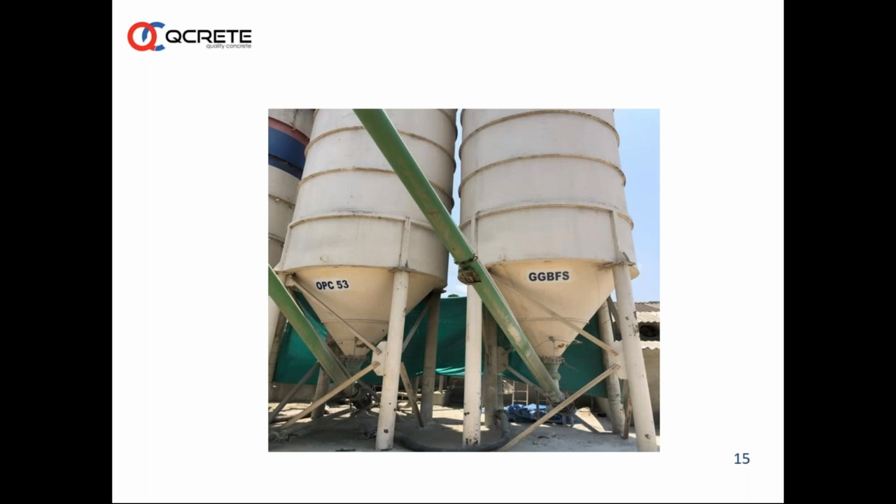So identification of silos which are meant for storing different cementitious materials like fly ash, GGBS or OPC has to be marked, and the batcher and the QC people should be able to clearly identify which cement or which material is in which silo. There should not be any case of intermixing or contamination of one product with another, which may cause a disaster.